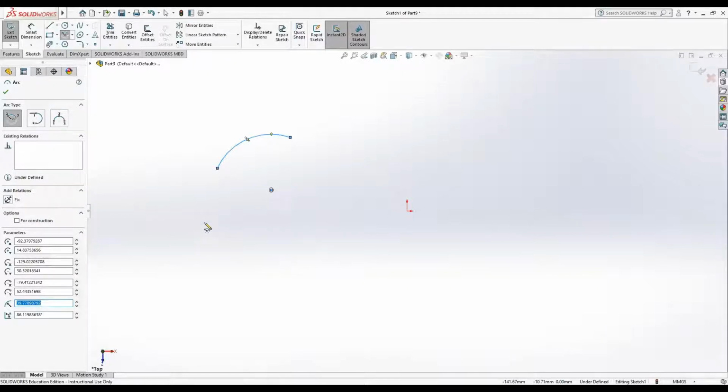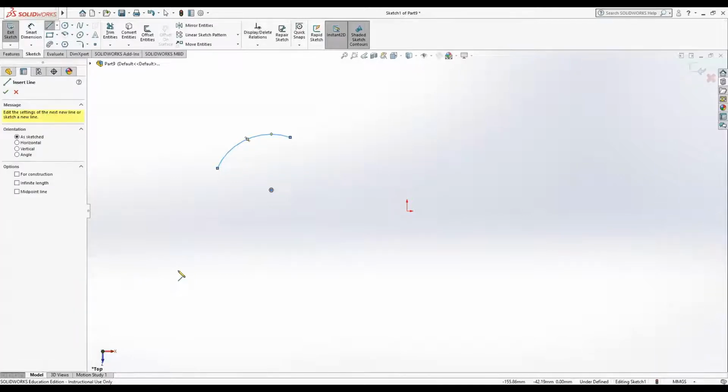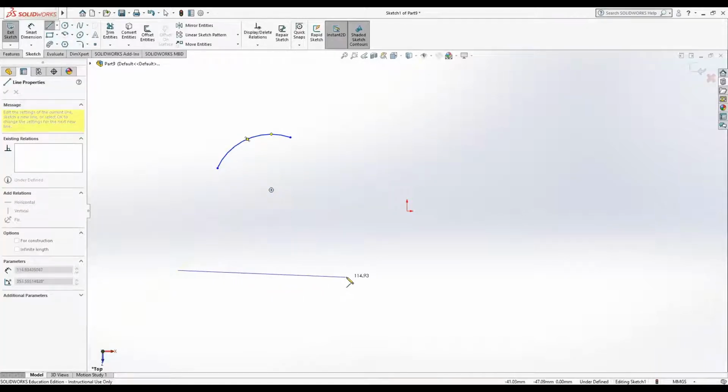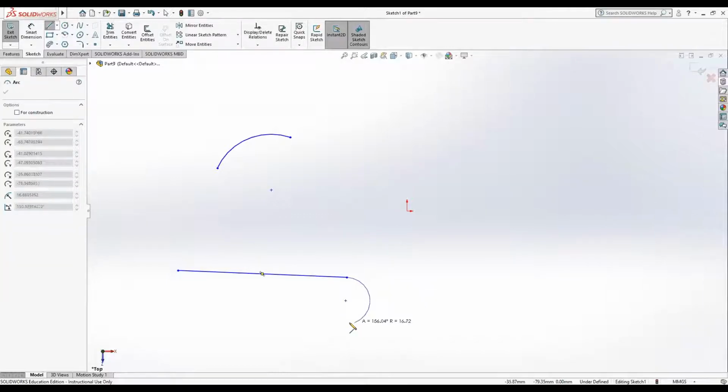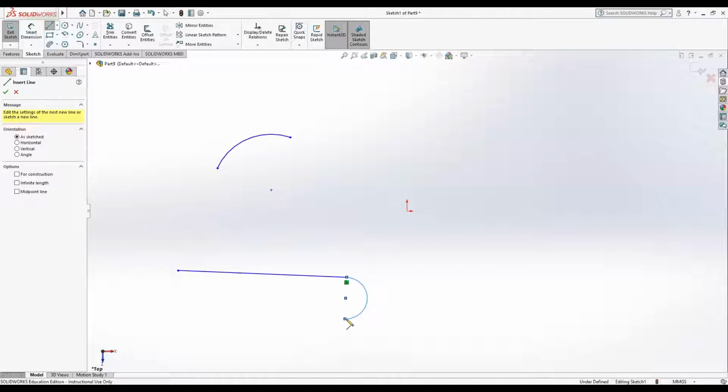So pretty useful. The other type of arc we have is a tangent arc. I'll show you that actually with the line tool here. If you're drawing a line and you put in your second point, you can continue on at an angle or a straight line. If you go back to that point, it gives you this little circle indicator around your mouse pointer, and at that point in time you're actually drawing a tangent arc. As you see there, it shows your radius, it shows you the degrees that you've traveled around that circle, and then you just click again and there's your tangent arc.